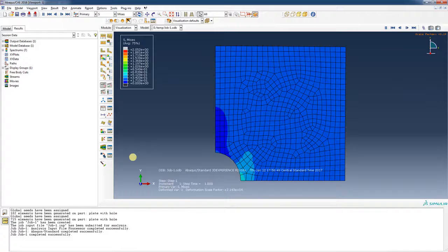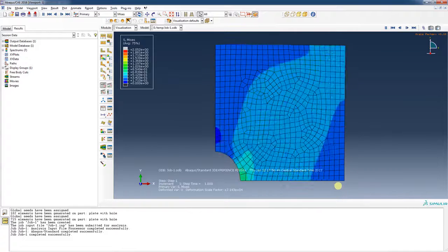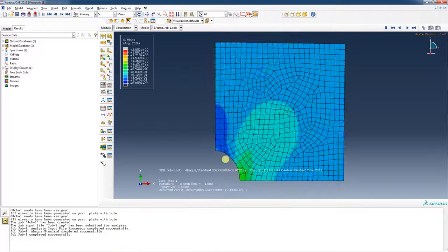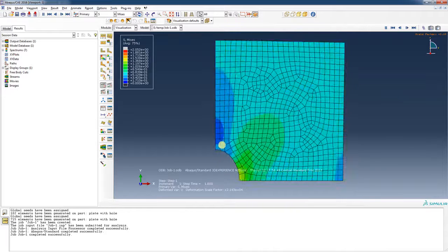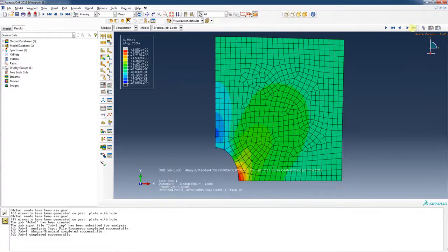And it appears to be behaving the way that we think it should be. You see on the right edge it's kind of drawing inward, it's just pull and tension, and this is sliding straight up. It's not pulling away from that line of symmetry, so it's good. Let's advance to the last frame, and this is on the von Mises stress. We're going to change it to the stress in the vertical direction, the S22 stress, and the highest value looks like 2.117.